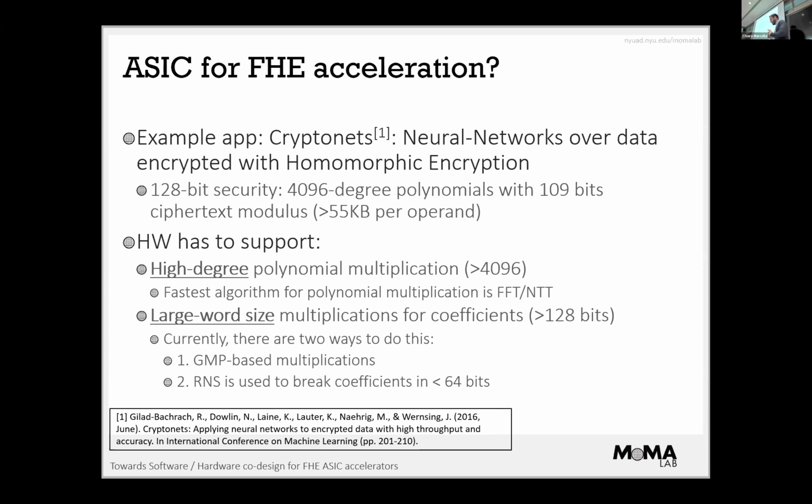So the hardware we need to design needs to support two things, right? One is polynomial operations, because we don't compute on big numbers, we compute on polynomials. So we need to work with polynomials, and every paper you have read so far has NTT as part of the processing. Why? Well, because regular schoolbook polynomial multiplication is n squared complexity. NTT brings it to n log n, so that's why we love it. So every polynomial multiplication in modern literature is NTT-based. Same, our work is the same.